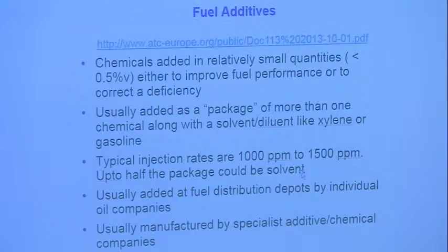And typical injection rates are 1,000 ppm to 1,500 ppm for the whole package, of which up to more than half could be simply solvents, like xylene. And they're usually added at fuel distribution depots by individual oil companies. Because, by the way, most oil companies, when they sell the fuel, take their fuel from the nearest refinery, which may not belong to them, generally speaking, because otherwise it would be too expensive.